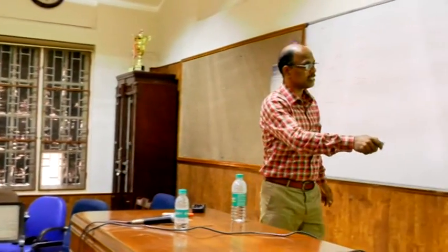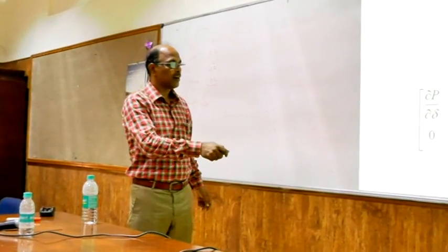The first equation represents dou P by dou delta times delta equal to delta P, and the second set of equations is the other. So this represents the first equation and this represents the second equation. The problem can be split into two small problems instead of one larger problem. Say, for example, a 1000 bus problem, where the size of the whole matrix is 1000. Instead of 1000, two small 500 by 500 matrices can be inverted.